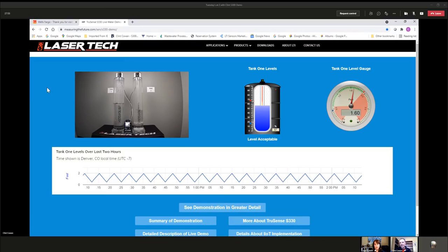We don't have any limitations regarding dielectric current or properties of materials in the liquid because we're an optic technology. We're looking at the surface of the liquid, and that's all we care about. We don't care about what's in it, what its dielectric property is. It makes no difference to us as a technology for measuring. So we're actually a lot easier to set up because we don't have to factor those things into the equation.